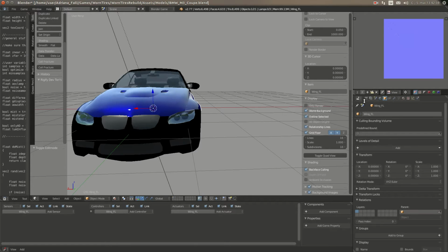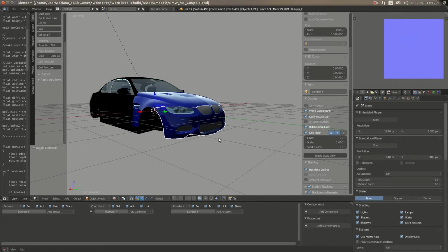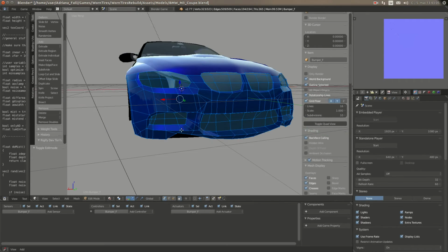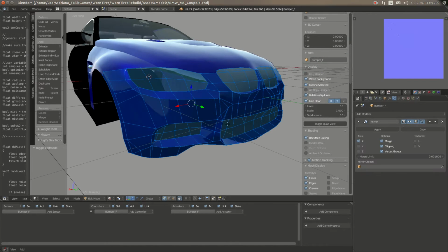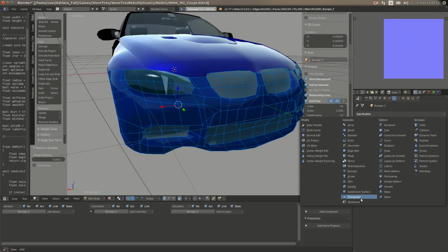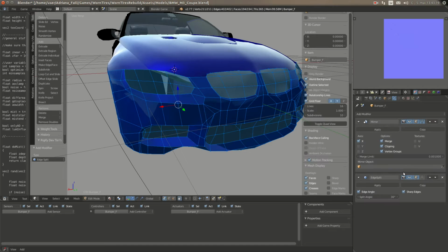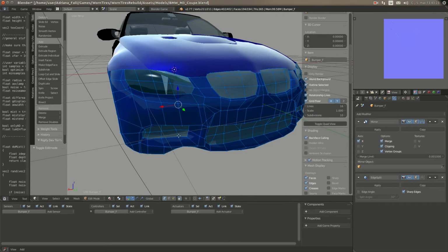Great, we've UV unwrapped one more object, and I think that we could actually work on the front part. So again, I'm gonna remove doubles and add edge split. Where is it? I just lost it. Okay, and remove edge angle, and let's mark the sharp edges.